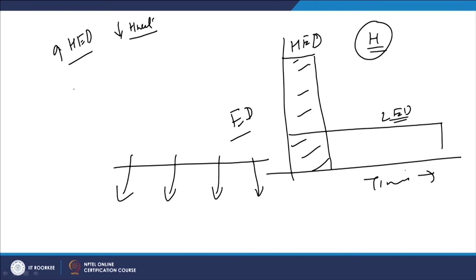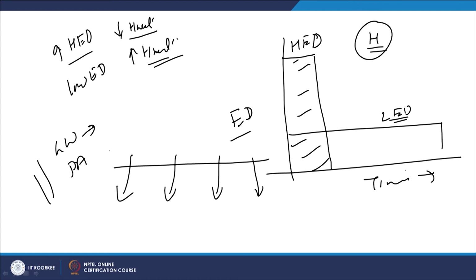The reverse is true for a low energy density process, which will require higher heat input. So, gas welding will require higher heat input as compared to plasma arc welding, and if for gas welding the heat input is high, it will offer a very large cross sectional area of the bead on plate, a lower cooling rate, and it will lead to a coarser grain structure, and this will degrade the quality of the weld surfacing which is being produced.